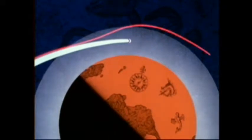If the spacecraft enters at an angle shallower than that of the upper or overshoot limit of the corridor, it will skip off the atmosphere like a flat stone off a pond of water, and go into an orbit that will not allow it to re-enter until its oxygen and power are exhausted. If the spacecraft should enter at an angle steeper than the lower or undershoot limit, the high G-forces involved would incapacitate the crew and could exceed the spacecraft's heat and structural capacities and cause it to burn up like a meteor. Therefore, to achieve safe entry, the spacecraft must follow a trajectory within the entry corridor.